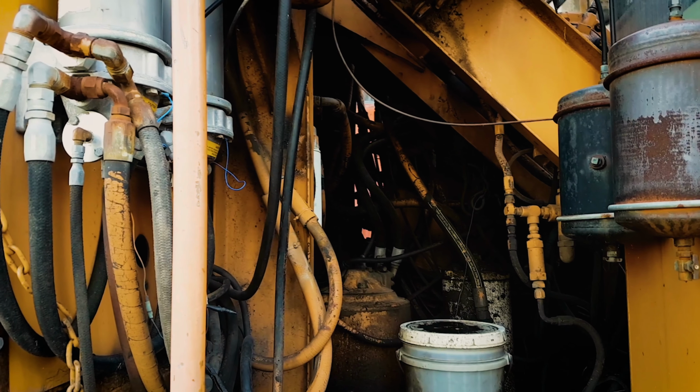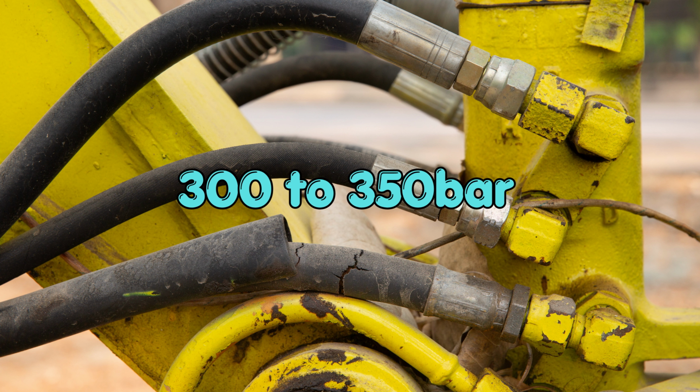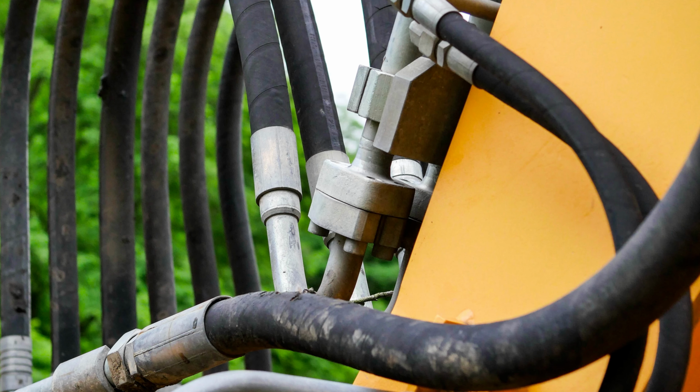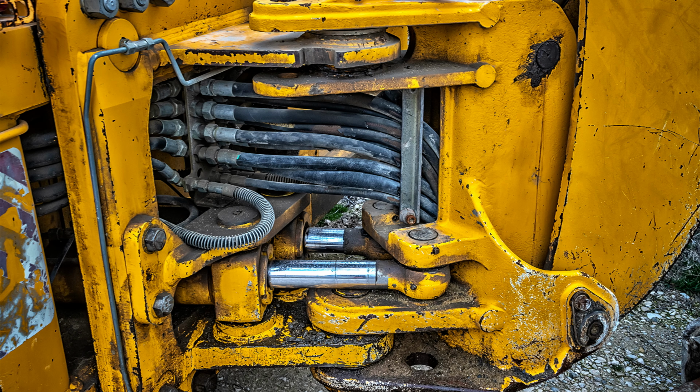This process generates continuous flow within the hydraulic circuit, supplying pressurized fluid to the system components for performing mechanical work. In modern excavators, the hydraulic system typically operates at pressures ranging from 300 to 350 bar, depending on the machine size and design. This high-pressure oil is then routed through the main control valve and hydraulic lines to different actuators in the machine. The control valves regulate the direction and amount of oil flow based on the operator's joystick input. From there, the pressurized oil reaches the hydraulic cylinders, which convert the hydraulic energy into linear motion.